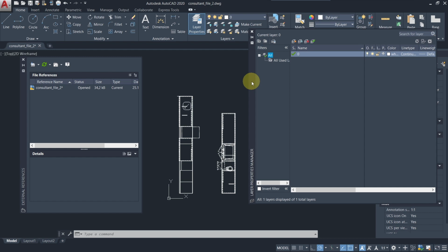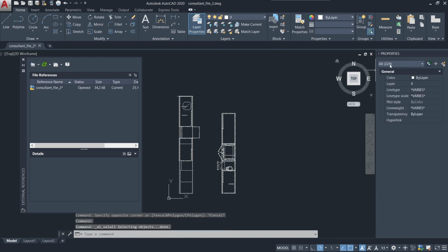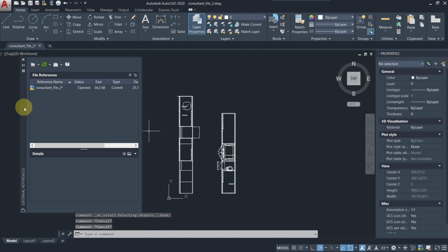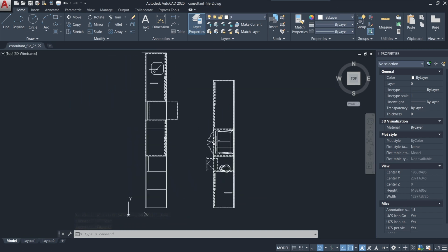Check also in 3D for the 3D geometry. Always explode all of the blocks and delete all the geometry that is not needed. And you should aim for having only like 2D geometries. As you can see here, lines, ellipses, circles, arcs, polylines, and so on and so forth. So this way, if you prepare your DWGs like this, it will be much easier for Revit later to work, and it will not be slowing it down that much as if you did not do this.